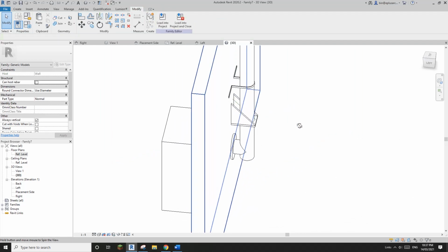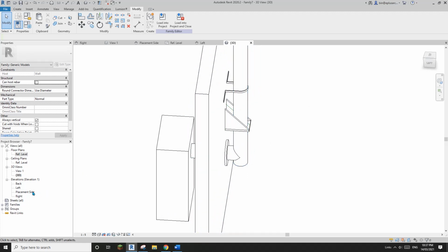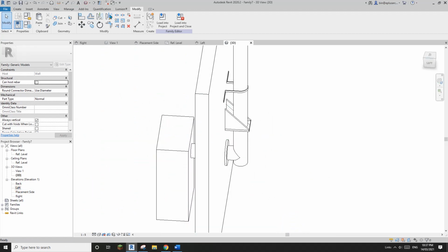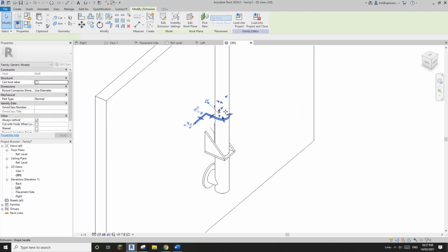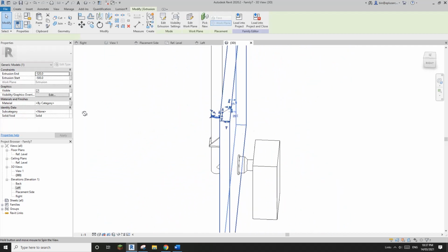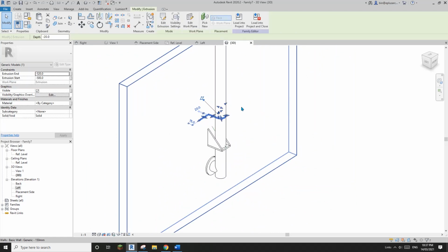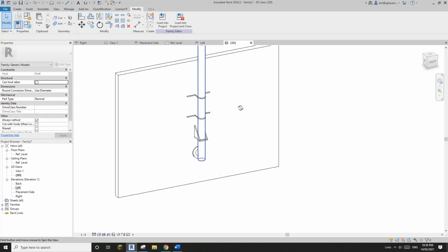Okay. Looks good. If you need to adjust the offset of the chimney, because we didn't create a parameter for it, you will probably need to adjust it manually. But that's it. That's the one. So Control C and paste in the same place. This time add another 500, so make it negative 1 meter and negative 1020. So we have another one.